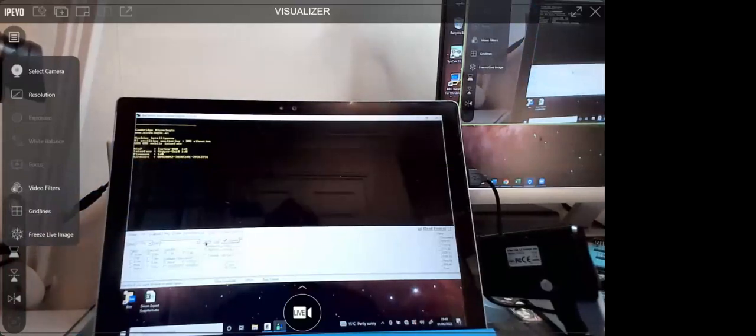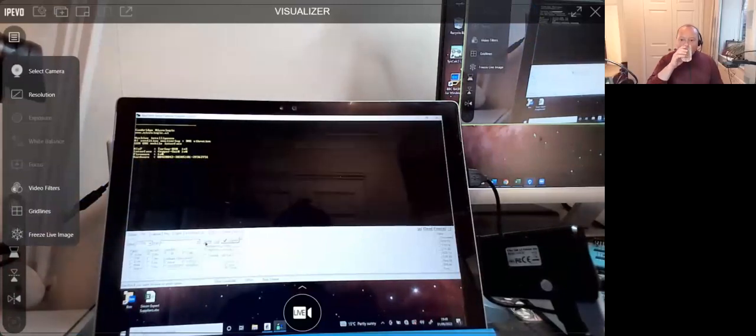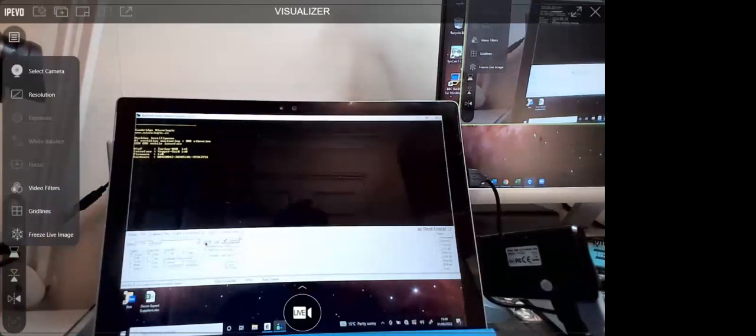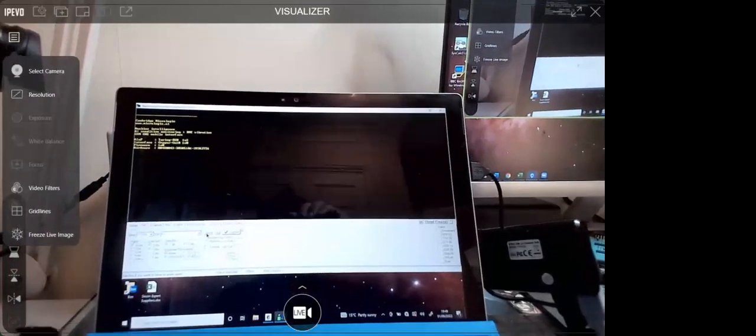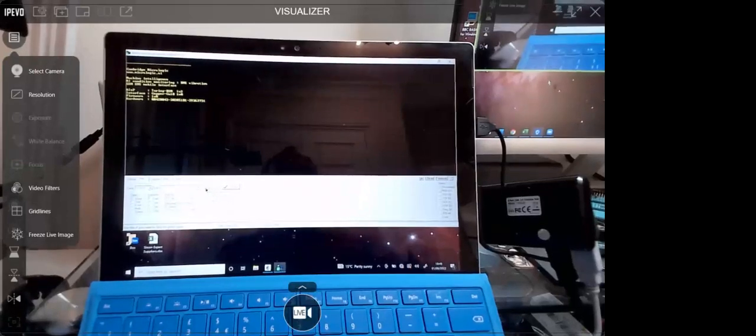Stephen? Yep. Apologies for another interruption, but you did say. Yeah, I did. One thing to note, if you're using a proper hardware serial port rather than something bit banged or whatever, make sure that you disable hardware flow control, or you will have very mysterious lockups and no output.